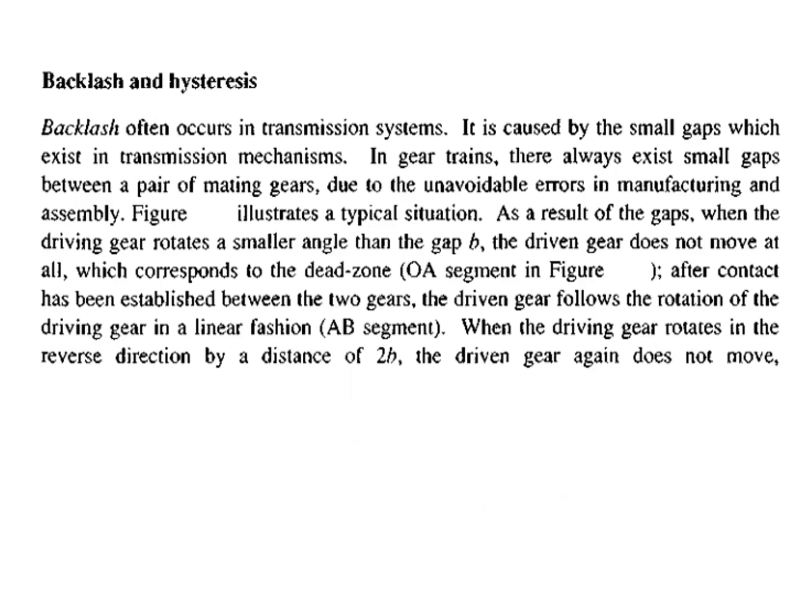The next type of nonlinear element is backlash and hysteresis. Backlash mainly occurs in the transmission system. It is caused by a small gap in the transmission mechanism. In a gear train, there always exists a small gap between the pair of mating gears due to unavoidable errors in manufacturing and assembly. So this is also an incidental nonlinearity which is present inherently in the system. As a result of the gap, when the driving gear rotates by an angle smaller than the gap, the driven gear does not move at all, which corresponds to the dead zone.